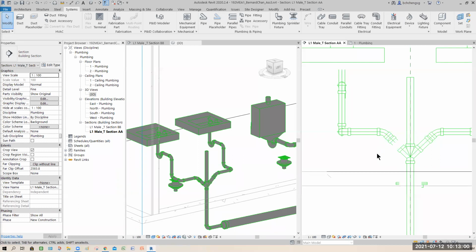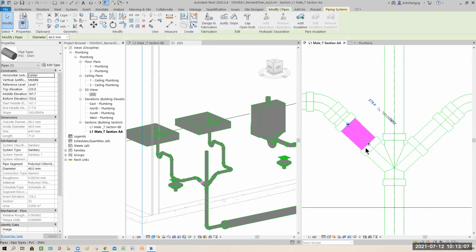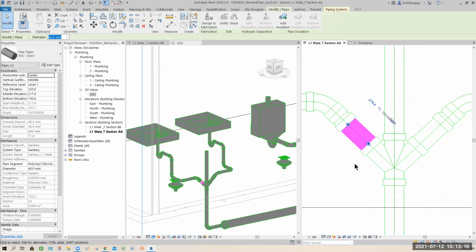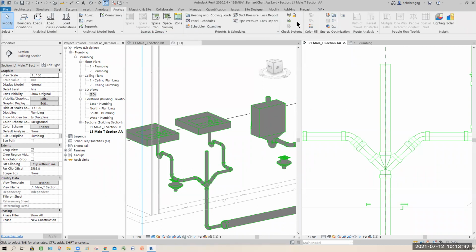So let's say based on the current view I can see from now, this one, you've got to select the pipe. You drag and you ensure that the O snap core point appears. Then you let go. And then it now should be connected. See? So this is the step you must remember to do. If not, later, if you just mirror, you go to analyze, you try to select the piping connection here, it says it's not connected. Sometimes it still does, but logically, when you do modeling, you must observe what you actually model out.